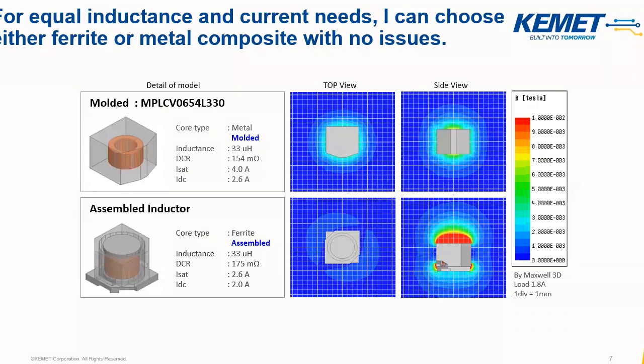So again, what you need to do is evaluate all of the pros and cons based on the way you're using your system, and also the mechanical configuration of the system, because if you've got, say, a ferrite material in close proximity to the air gap, you're going to be inducing eddy currents in that material that are close to the unshielded ferrite inductor.